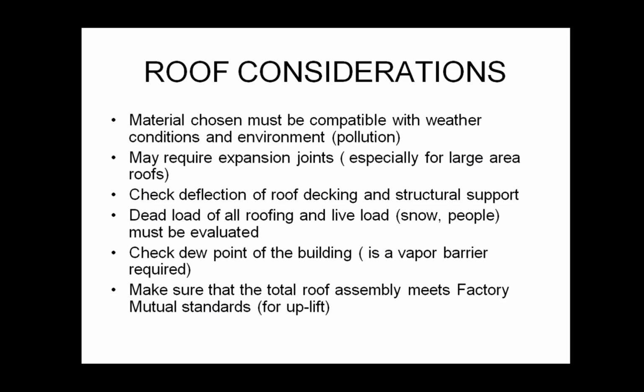The generals are to make sure that it's strong enough for the location that you're in, that it's built to handle the type of weather that you're in, that if it's a long or wide or very large roof, that you build in expansion joints just like you would on a concrete deck on a floor or on a sidewalk or on a roadway. And that if your roof has equipment on it, as many large buildings do, that you also have to be prepared to handle that load as well as the load of maintenance staff and personnel on top of the roof. So you can't have a flimsy roof